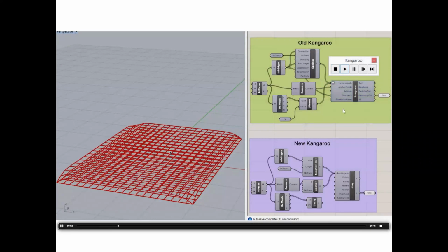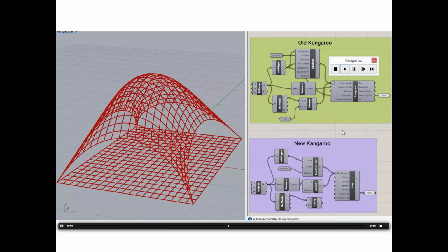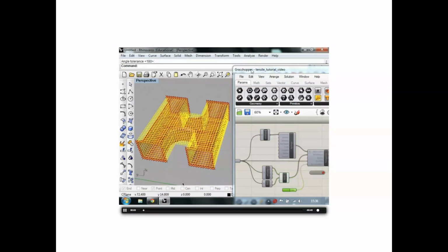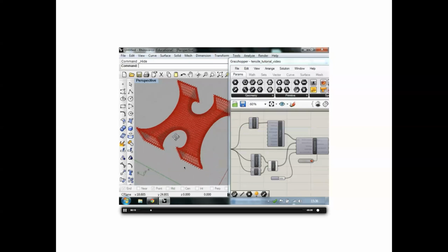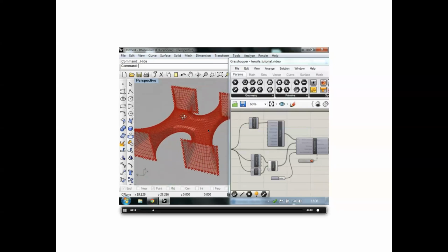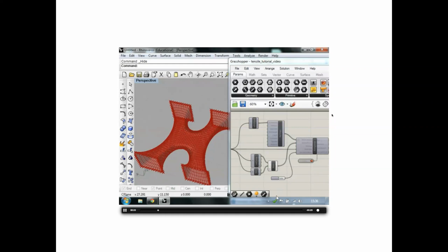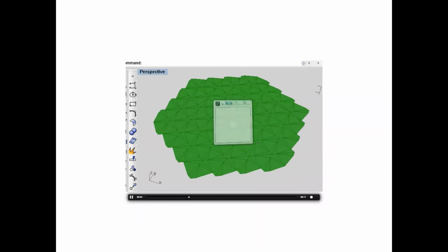Here's another example of form finding where we generate a catenary vault, right? So not just an arch, but an actual three-dimensional vault, using gravity and springs. We're going through a relaxation routine where this thing will spring and find a minimal tensile state. You can almost do it like you're bouncing on a trampoline, right? All of these become springs, just like on a trampoline. Suddenly it springs back and finds that equilibrium between the external forces and the internal forces, right? You can also take something flat and then do paper folding.